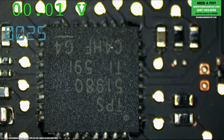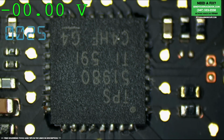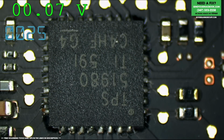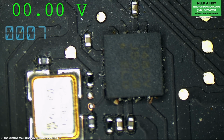So here we have the TPS51980 chip, and it looks like we have 0 volts on PM Sleep S4L. Bam! See? So now we're going to take a look around the board and see if there's anything that sticks out to us as to why that's not present. Sometimes it's not present because the clock chip is not creating a clock signal.